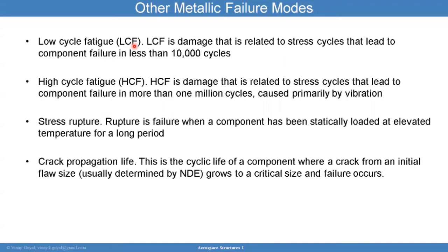While high cycle fatigue is more of a silent killer because you may not see any plastic deformation yet, dislocations and damage are occurring at the micro level until a crack will just initiate at some point and start propagating either catastrophically or in a stable manner or is completely arrested.